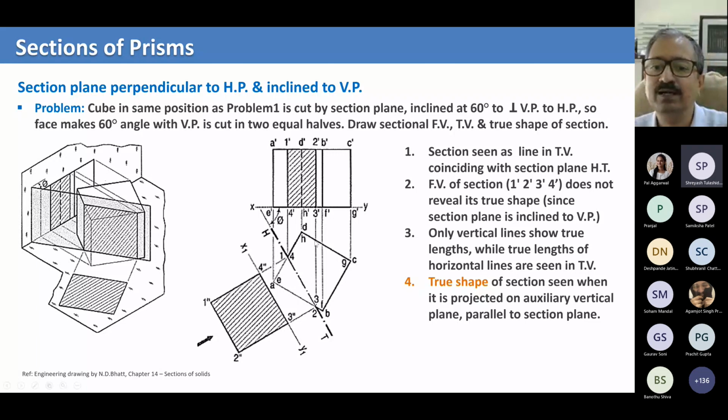If this cross-sectional plane passes through D, then this entire right-hand portion from this line would become cross-hatched. One side will be plain, one side will be cross-hatched. Here it is coming in the middle, so there is a portion of the cube both on this side and that side which is visible. So don't just look at one example, but also keep thinking about it in different ways.